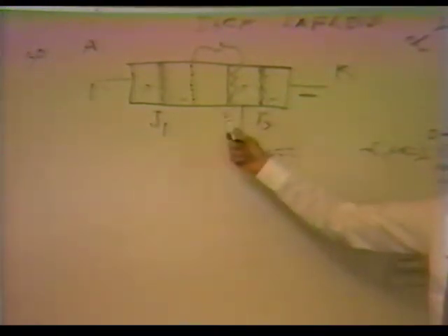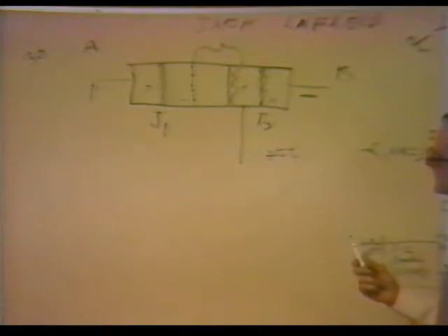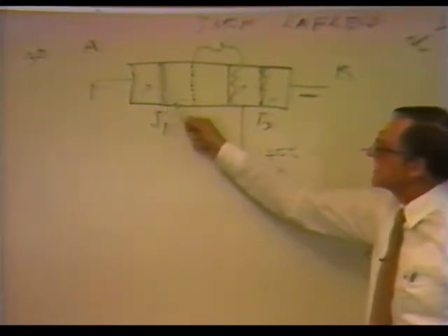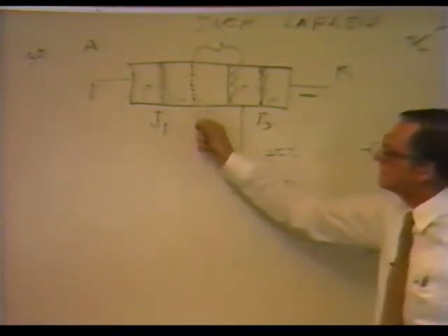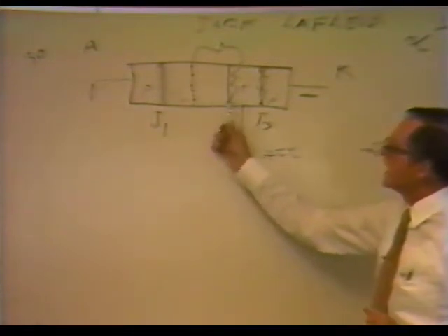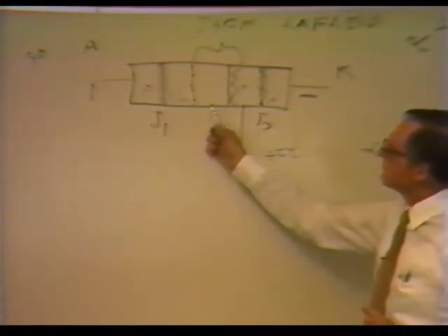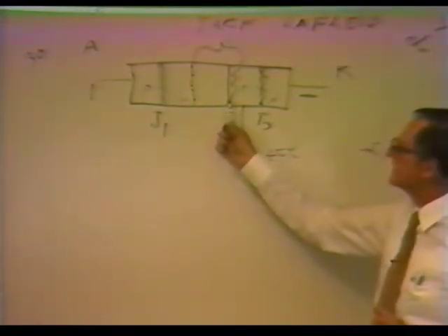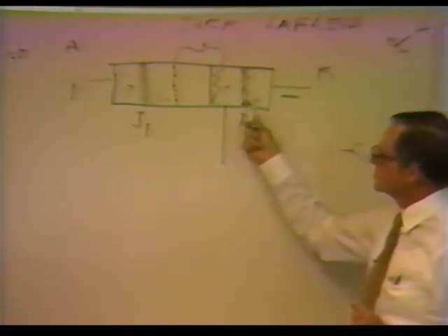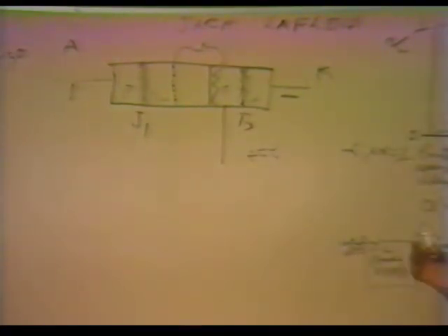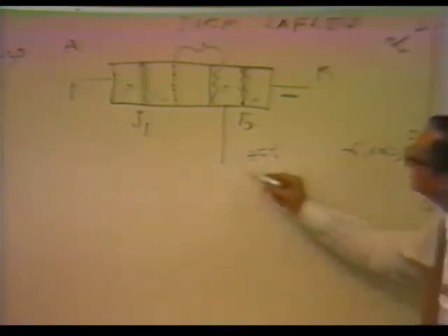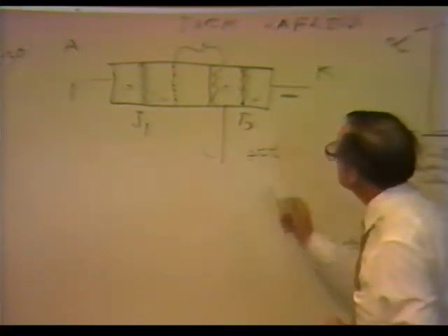Mother Nature likes everything to be at an equilibrium. So she has the junctions that stand off there and there's no activity. We applied 30 volts, and this blocking junction has sustained the 30 volts, and we have a forward bias junction here, and everything is calm. And you're holding off your voltage. Now you come along and you hit it with a gate signal.